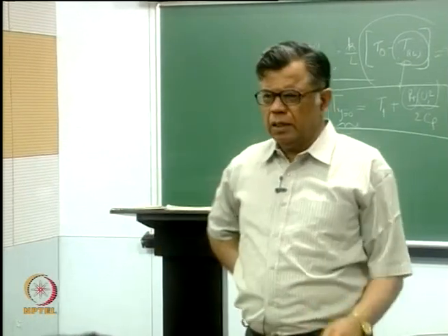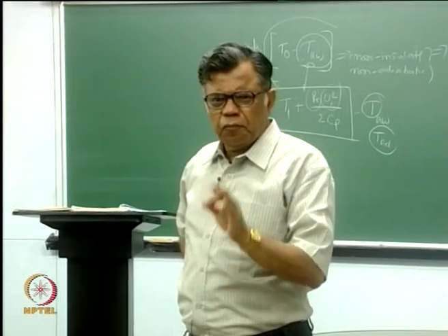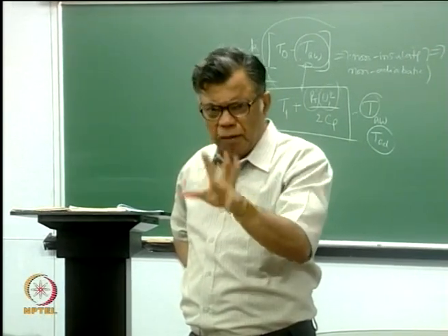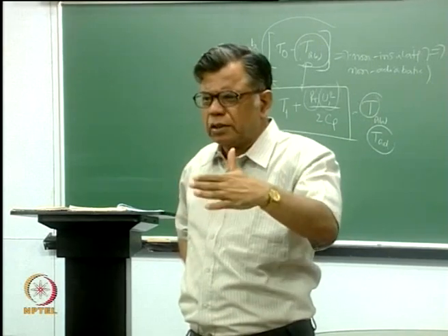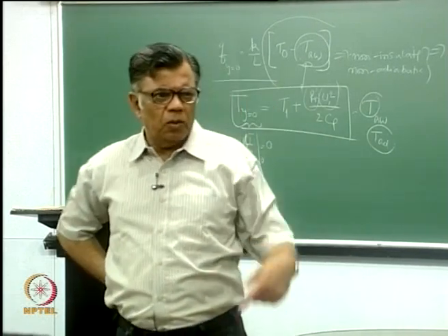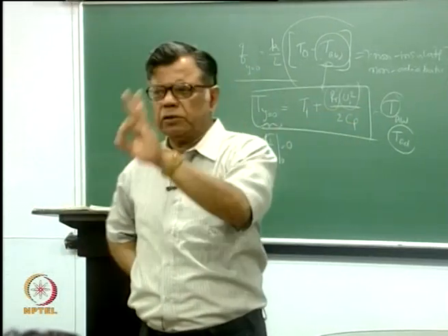We will go further. I wanted to bring to the point here that R is a function of Prandtl number only in terms of number, but it changes from situation to situation in terms of the geometry and the flow. So a flat plate laminar problem has a certain recovery factor, which is a function of Prandtl number.